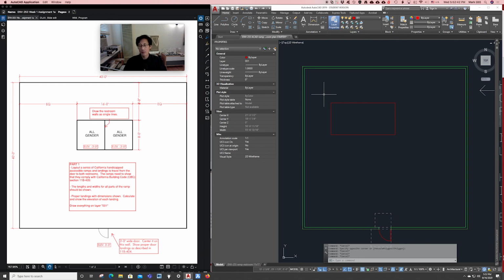Just to demonstrate also, there's in AutoCAD a difference between pre-picking and post-picking items. I've been demonstrating pre-picking, which means I select the objects first and then issue the command. I can issue the command first, move, enter, and AutoCAD asks what objects I want the command to work with, and then I can just select those. After I'm done selecting, I hit space or enter again, and then I continue with the command as we've been seeing.